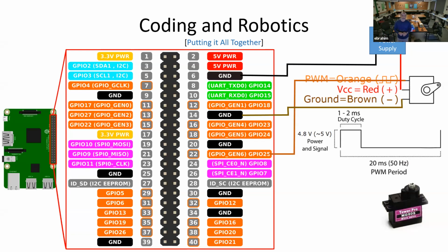And if you start drawing too much current, what will happen is that the current basically comes from the Raspberry Pi, and eventually you can overload the power supply of the Raspberry Pi, and the Raspberry Pi will stop working. You can blow it out because you're trying to draw too much current. In order to prevent all those problems, what we have done is we have put out an external power supply, which is a 5-volt power supply on the top here. We put this here, external, and then we are powering that servo motor with an external power supply and not the Raspberry Pi power supply.